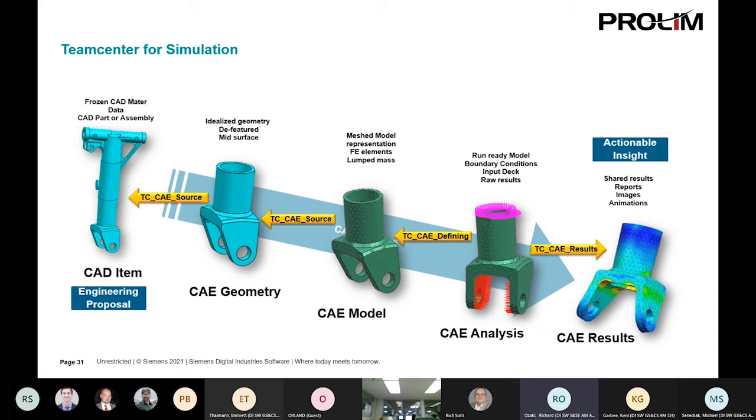If you think about the designed geometry that the CAD team has created, maybe it looks something like this, part of an aircraft landing gear. When you then go to perform simulation, there is a level of simplification or at least some sort of modification that needs to be performed on that geometry before it's ready for analysis. So maybe you remove some of the parts that aren't needed. Straight away, we're deviating from the original CAD geometry.